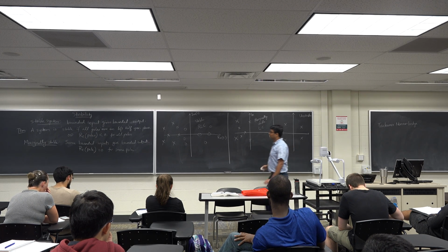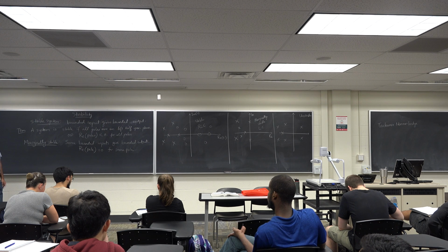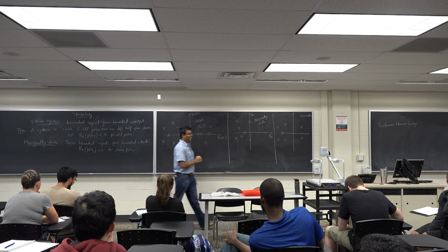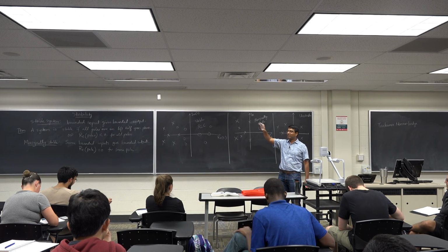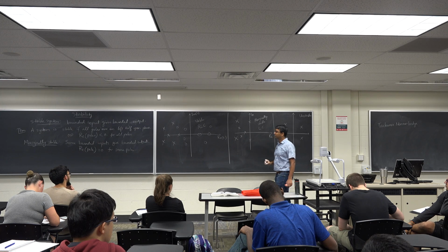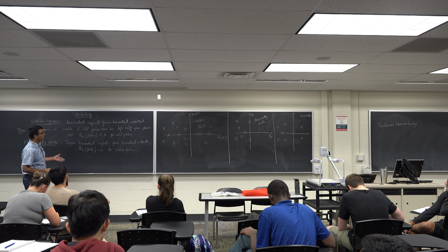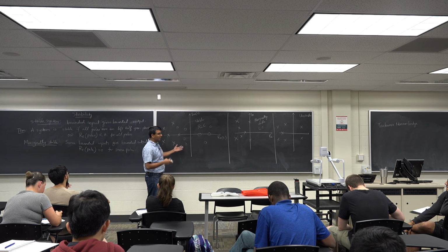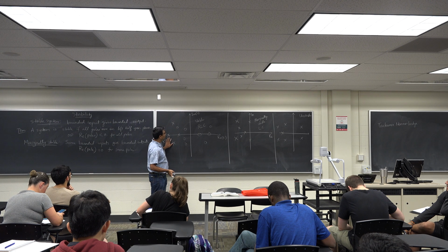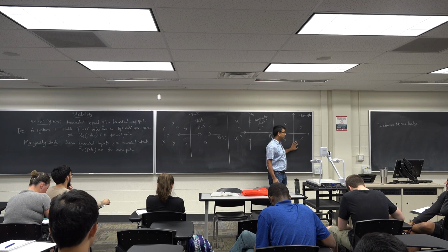All right. Now, this idea of stability goes back to James Clerk Maxwell, whose wave equations I'm sure you must have studied, and I don't know whether you liked it or not, but I certainly didn't like it. He was also the first person to write the first paper on feedback control systems back in the 1860s. Around that time, people were working on these ideas, and they figured out that if your poles are in the left half plane, your system is stable. If your poles are on the right half plane, then the system is unstable.